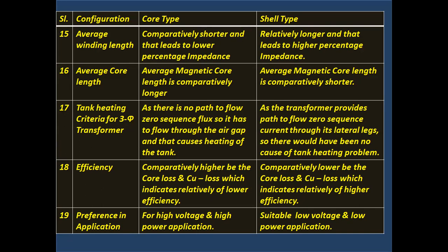Tank heating criteria for three-phase transformers. As there is no path for zero sequence flux to flow, it has to flow through the air gap, and that causes heating of the tank in the case of core type. But for shell type, as the transformer provides a path to flow zero sequence flux through its lateral legs, there would be no cause of tank heating problem.